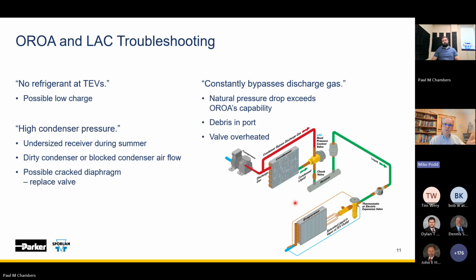But you can also calculate how much of that condenser is flooded if you're charging it below, let's say, 70-degree ambient, using our calculation tables. You can say, I'm charging it today and it's 40 degrees outside with my valves already set.